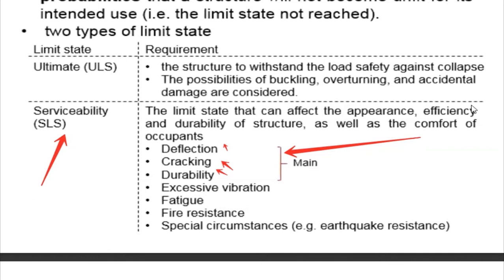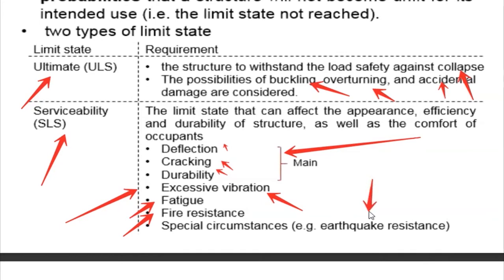But once you consider collapse, accidental damage, overturning, or buckling, we say the structure is safe under the ultimate state. Further consideration goes to vibration, fatigue, fire resistance, and even the earthquake. And this is the consideration for the serviceability limit state.